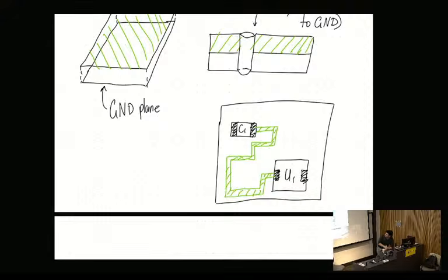So what's not good about routing a PCB like this? I wanted to go from one end of C1 to the clock generator down there. What's not good about this iteration of PCB? I promise I don't design PCBs like this. Super long. Yes, so it's maximized. So why is that bad? More inductance along the line. So our goal for the question was to minimize the amount of parasitics on one of the nodes. I've just added lots of parasitics with this very long trace.